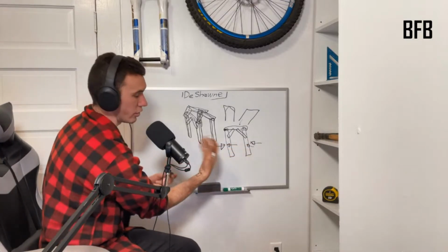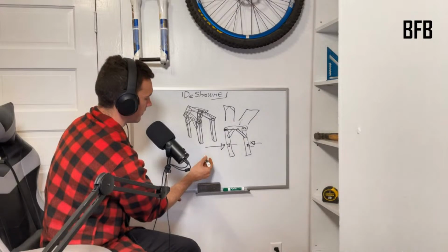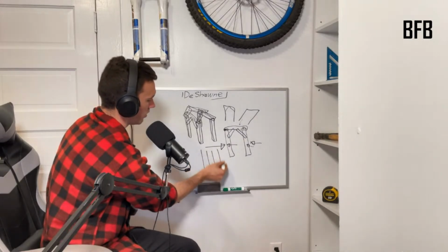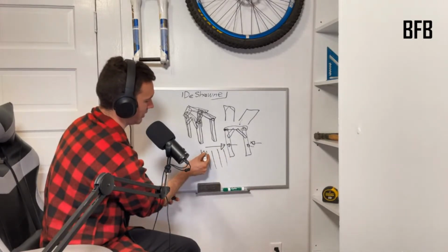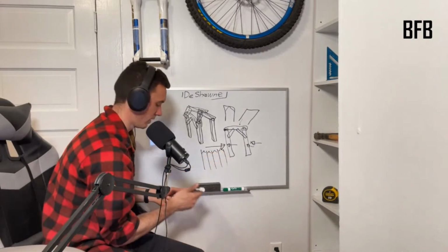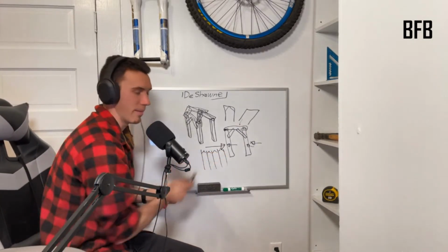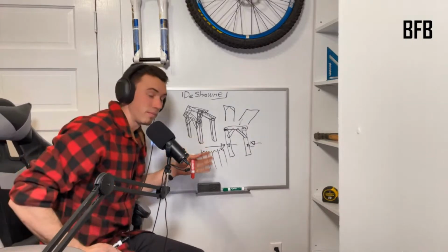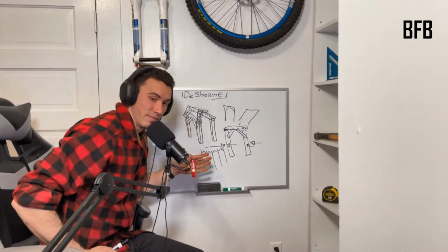So if we build a wall where all of these vertical members that they used to call posts turn into studs, well, if we have a big stud wall with a bunch of studs, we're not going to add a whole bunch of tiny little blocks of wood at angles like this. That would be kind of silly now, wouldn't it? So we don't do that. What we do is we create diaphragms.